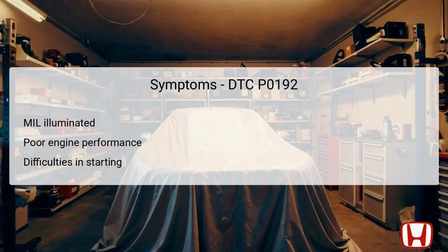One of the most immediate symptoms is the illumination of the malfunction indicator light, or MIL, on the vehicle's dashboard. In addition to the warning light, the driver may experience a decline in engine performance. This may manifest as hesitation during acceleration, rough idling, or an inability to reach higher speeds due to improper fuel